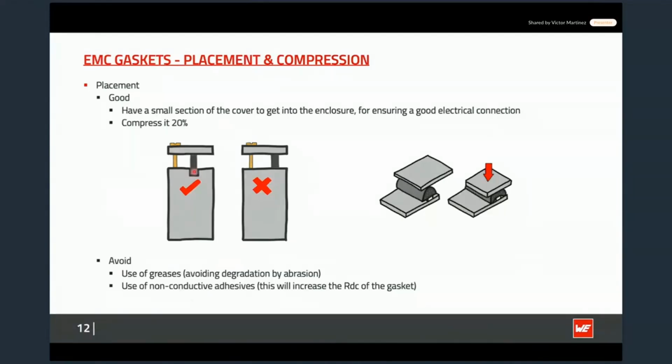And at the same time, you're ensuring that the gasket won't move. Because if you place it without leaving any kind of groove, and the gasket is really thin and tall, the gasket could just slip out, forming a kind of L to the outside or to the inside, so you probably won't be able to ensure good conductivity between the top surface and the bottom surface.